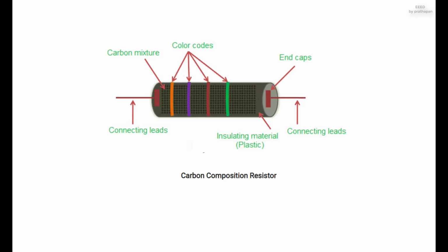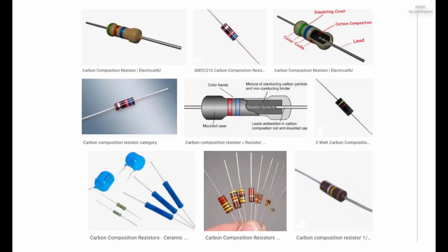Carbon composition resistors were commonly used in the 1960s and earlier, but are not popular for general use now as other types have better specifications, such as tolerance, voltage dependence, and stress. Carbon composition resistors change value when stressed with overvoltages. Moreover, if internal moisture content, from exposure for some length of time to a humid environment, is significant, soldering heat creates a non-reversible change in resistance value. Carbon composition resistors have poor stability with time and were consequently factory sorted to, at best, only 5% tolerance.